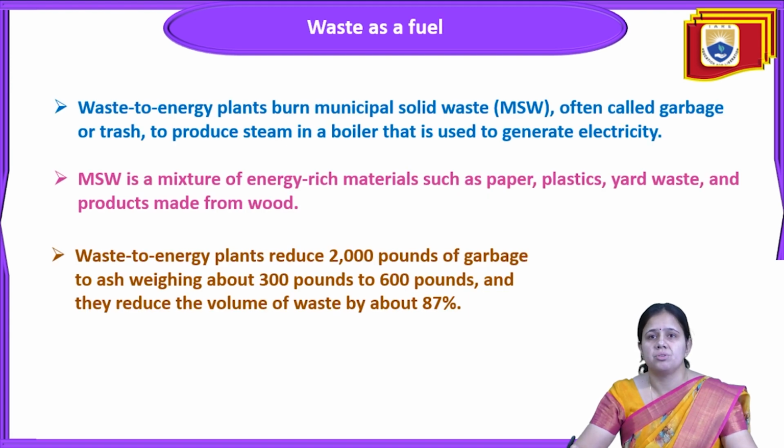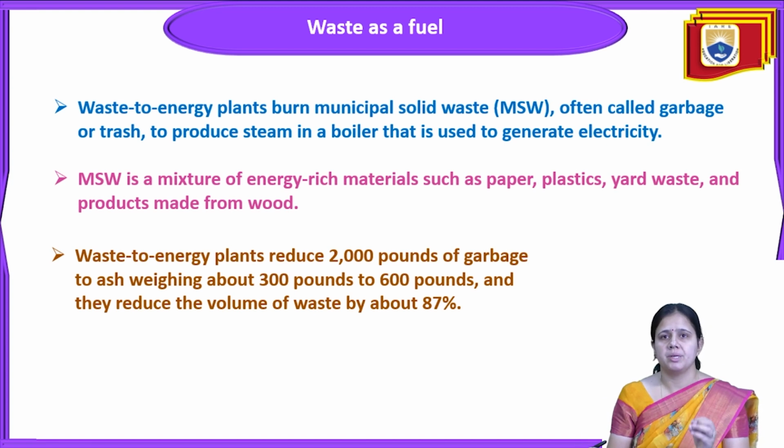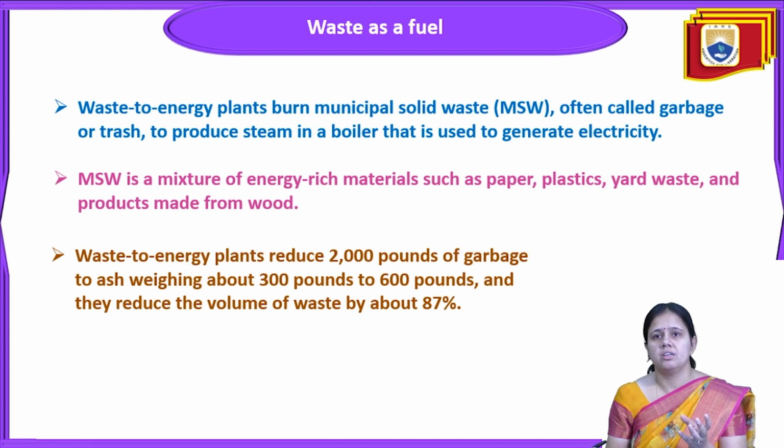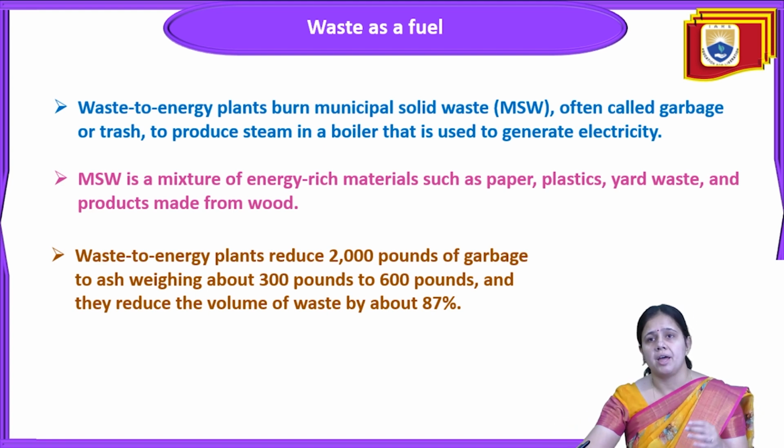So for waste as a fuel, we'll discuss waste to energy plants that burn municipal solid waste, basically called garbage or trash, to produce steam in a boiler that is used to generate electricity. So in a boiler, this garbage, this trash or solid waste is burned, and by the burning of this solid waste, heat comes out, and this produces the steam in the boiler, and by this steam we generate electricity.